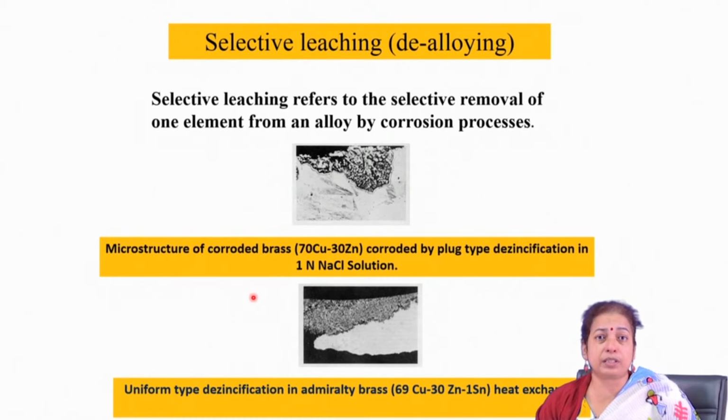But otherwise, if you are interested in taking care of this problem by surface treatment, you have to go for a typical surface melting operation, that too by the application of a high energy beam like laser or electron beam, where you melt the surface and then quench it very quickly, so that there is no chance of any chromium carbide precipitates, and that steel on the surface is highly free from any chromium carbide. So, whenever this problem of intergranular corrosion occurs or is observed, it is very important that you find the solution very quickly, so that this steel does not undergo any kind of corrosion in the service environment.